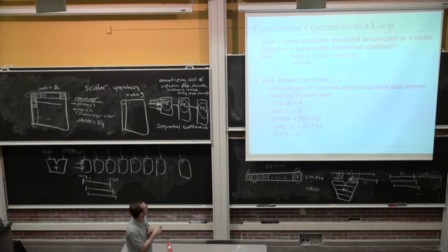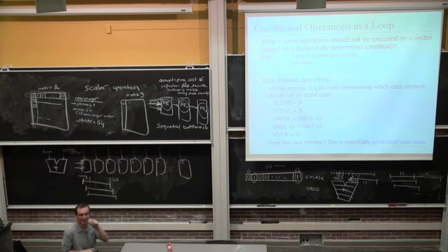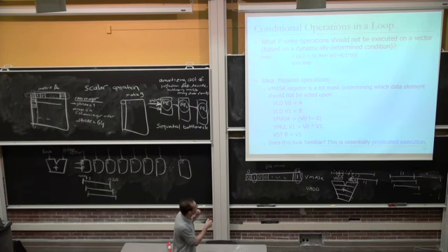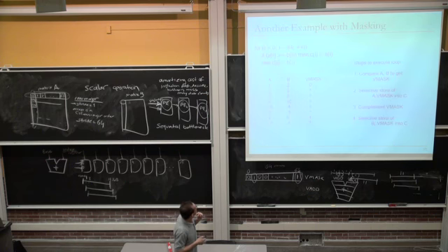I guess I should have asked you earlier, but this is essentially predicated execution, right? Your mask is really the predicates, and this multiply is really a predicated multiply. Each operation that the multiply does is predicated upon the mask bit. In fact, vector computers are the first computers that implemented predicated execution. This was in Cray 1. Cray 1 had these mask registers.